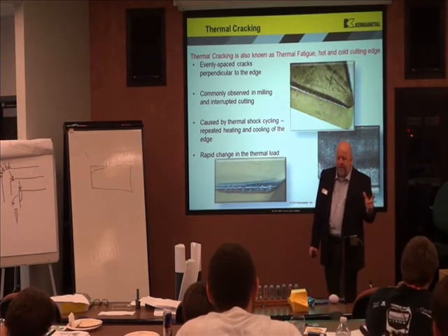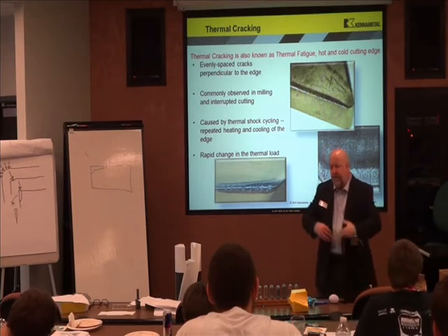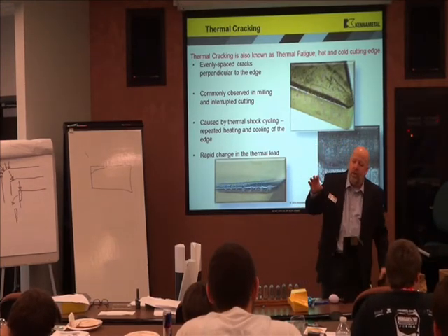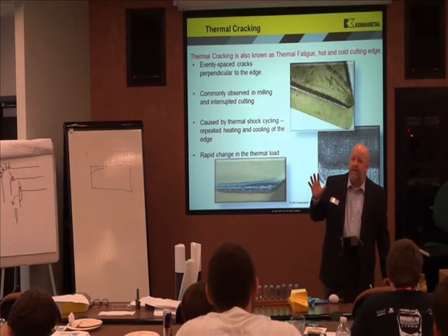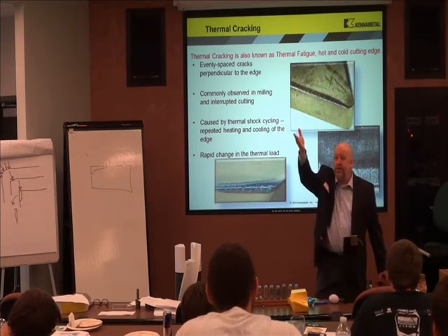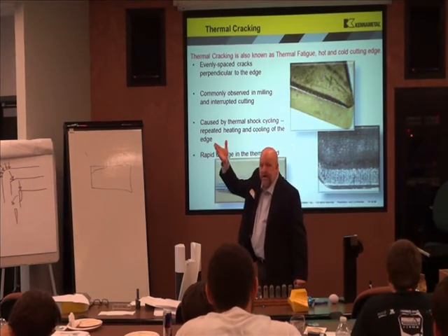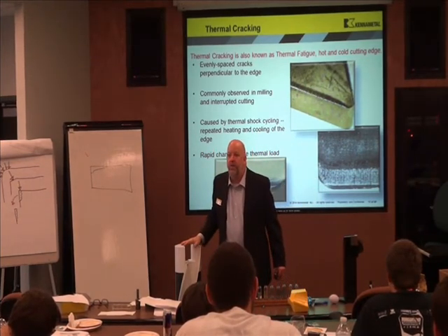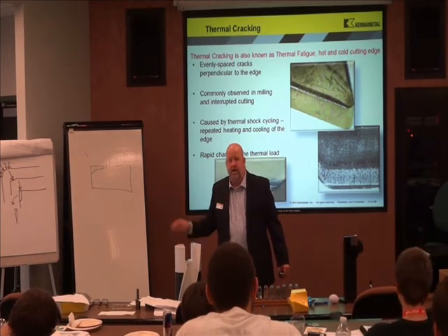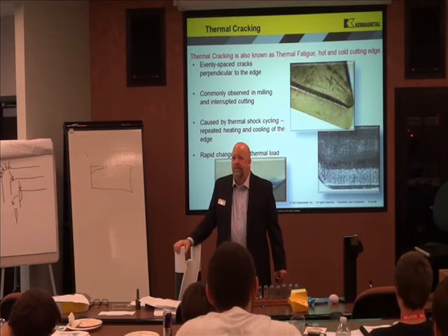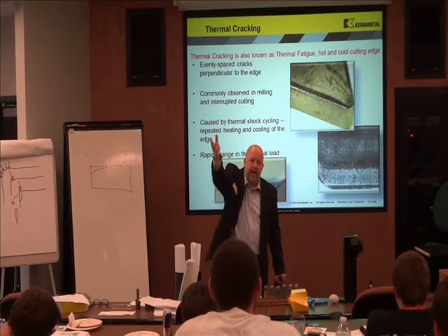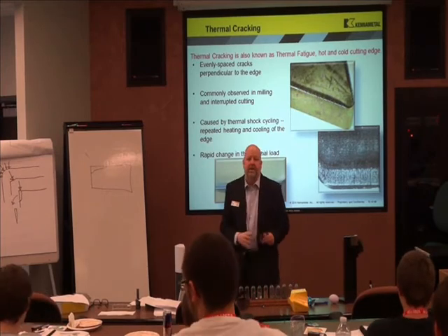True story. A lot of people use coolant in milling in order to get the chips out of the way. You're starting to see more manufacturers of CNC machines putting air blast, right? You're seeing it come through the spindle even, right? Yep. In some cases. They weren't that way 3, 4, 5 years ago, were they? Maybe 10 years ago. They weren't. We've been preaching this for a long time. Now the machine tool manufacturers are changing.